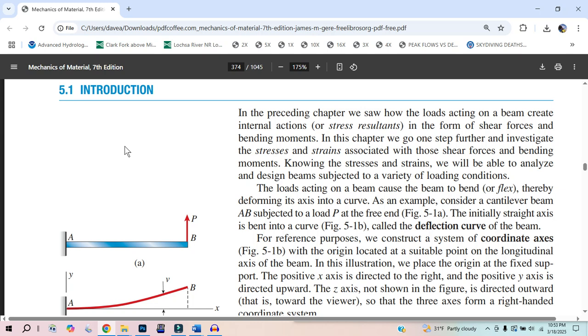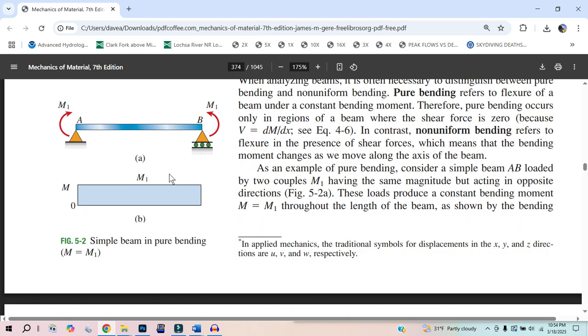So this chapter is going to be a more advanced chapter. What you would do to learn material mechanics is you would learn statics first. So if I put an upward load on this, well, it'll induce a shear force all the way through this member. So this is not a pure moment. A pure moment is when you do this. Let's say this was just a ruler and these are your two fingers that you're applying a twisting.